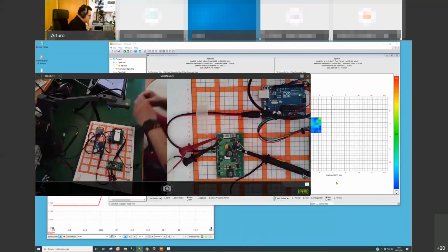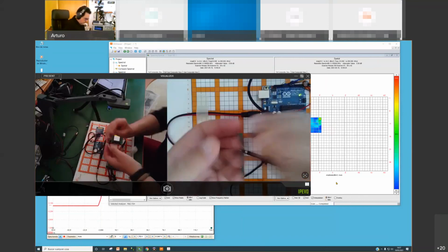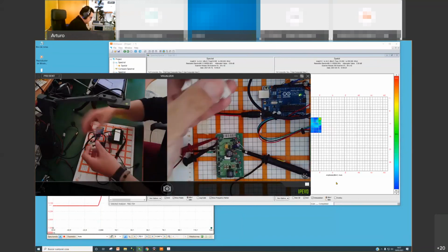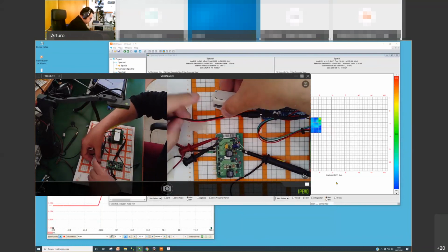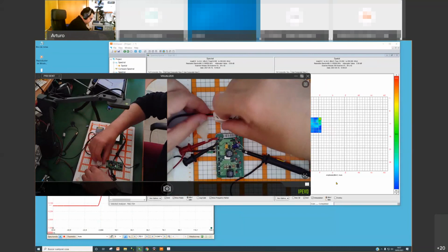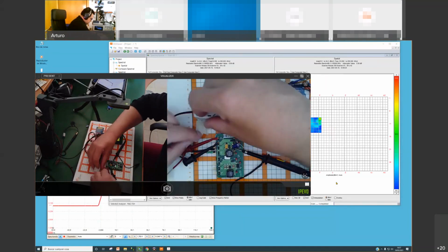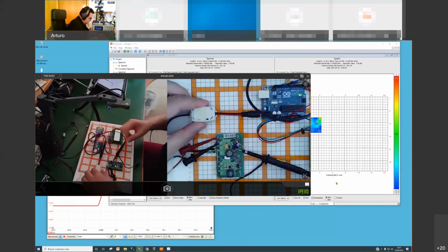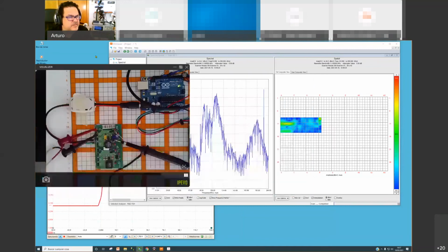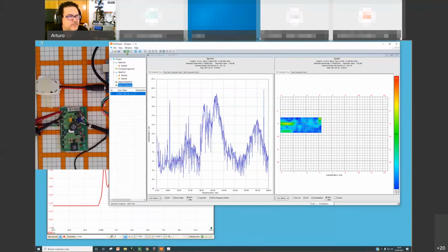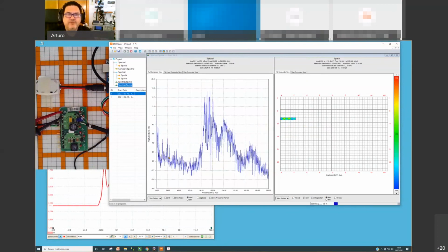Okay, so I open the ferrite and I move the cable to introduce the ferrite in this position, for example, this position here, and then I fix it again in position, and you can see the difference. Now we will repeat the same measurement, but with the ferrite in place. And then we compare. This way, you will be able to see the reduction in decibels with and without the ferrite, or comparing two different ferrites.